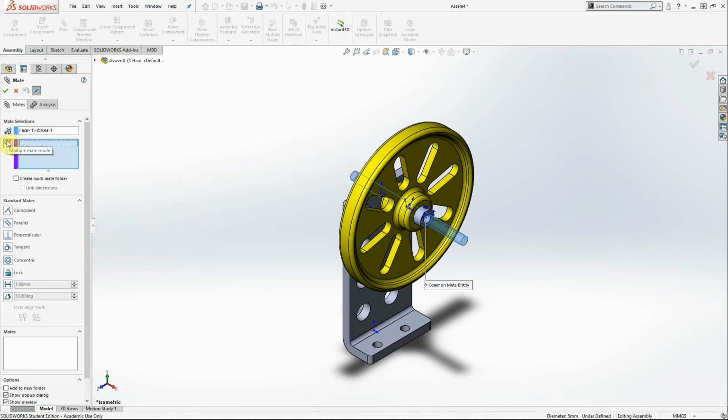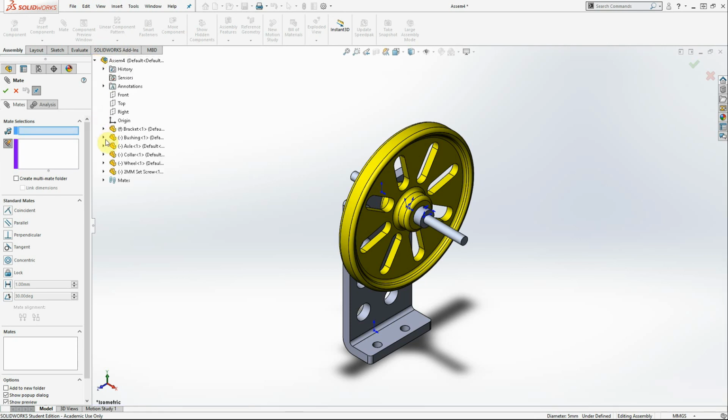and it's got the face of the axle. I don't want the face of the axle. Delete that. Our feature tree has now moved over here. Dialog here for the mating, feature tree over here. So I do want the axle. Top plane would work, right plane would not, front plane would work. So the axis of the rotation axis is in the top or the front plane.